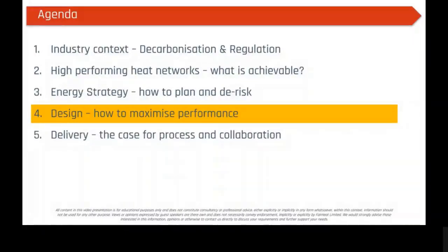So on to design. What I'm talking about now is predominantly the dwelling and the building design, because that's, as I said earlier, what defines what the heat network needs to do. But not just that, we actually find that it's the dwelling and the building, in terms of their design, performance and commissioning, that will dictate how well the heat network performs. When a dwelling is not performing well, the whole network suffers and there's nothing you can do about it in the energy centre. So there's a lot of attention that needs to be given to how we design and size those dwellings and buildings correctly to get the overall system to work.